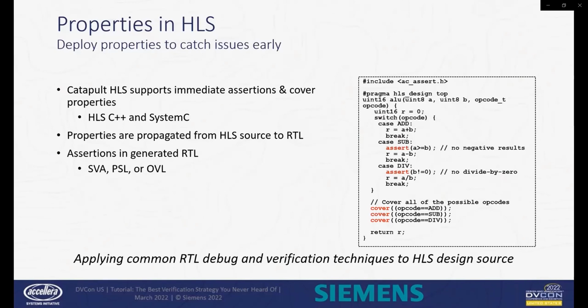And this is just the first of several examples of taking verification constructs we are familiar with at the RTL level and applying them to the HLS design source. And it is a useful debug technique, especially during RTL integration level testing.